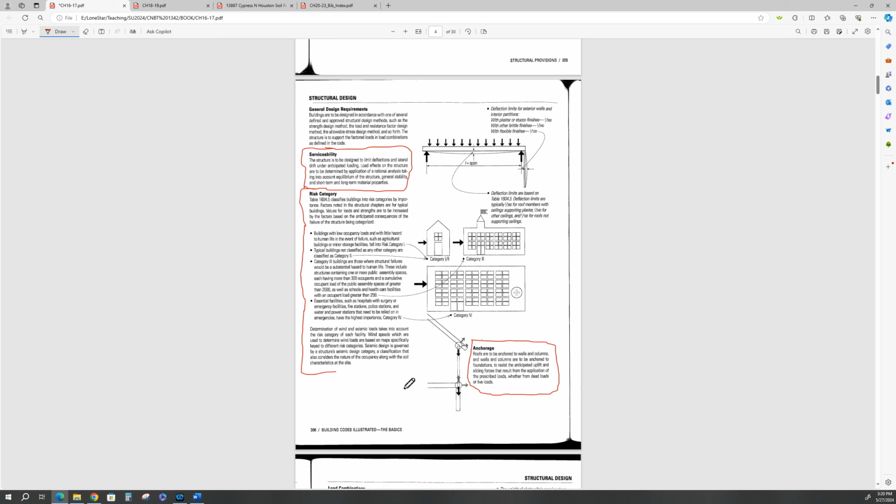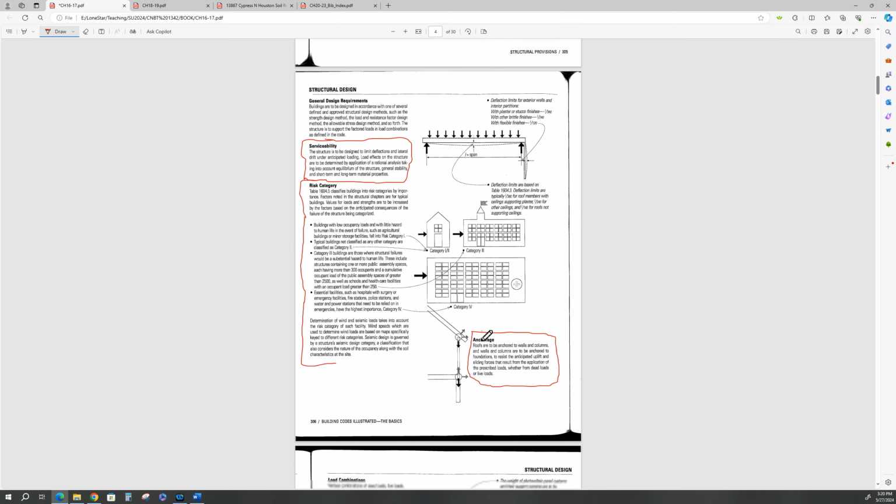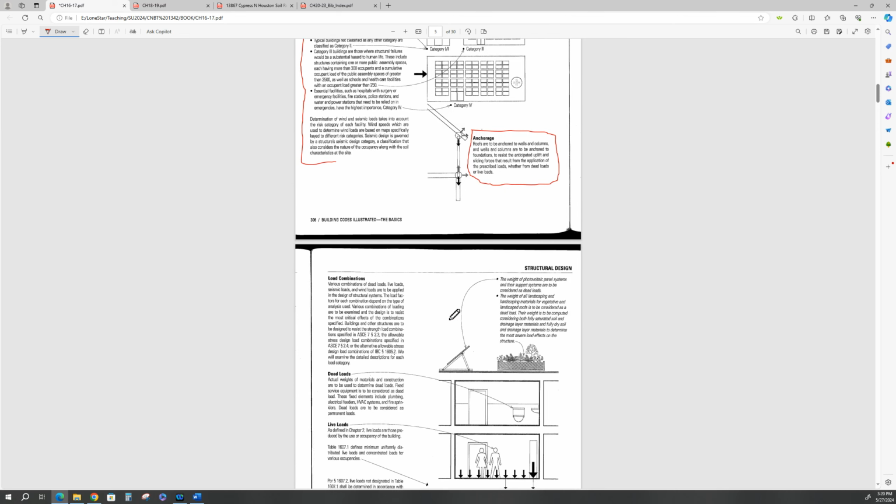Okay? So you got a wind load that comes through here. You want your building anchored to a good foundation so it doesn't slide off or tip over and rotate and flip over, right? So it resists uplift. It resists sliding and overturning of the structure. I mean, you don't want the building to slide. You don't want it to turn over, right? Okay.